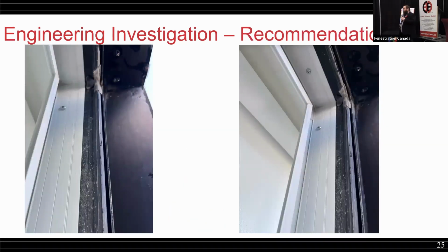This was one of my favorite failures. It looks like we did a temporary dam with plumber's putty, but no. Unfortunately, every once in a while, I am actually the person that the installer and manufacturer should hate because I point out that you put something in, and apparently I'm told this one came from the factory like this, which I didn't believe at first. And I still withhold judgment, but there is a sort of semi-elastic mastic fixing the gasket in the corner of this window, if you can believe that or not. And it was the source of the leak. The gaskets should never have been kept in place. They should have been replaced in their entirety.